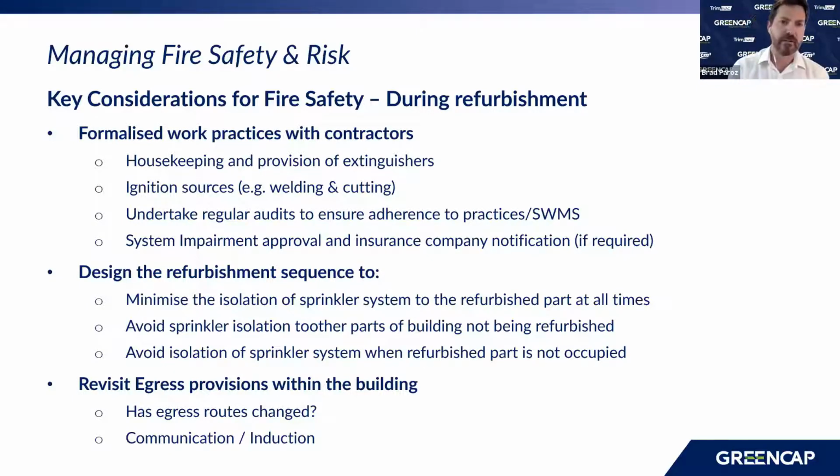Yeah, great. Look, dead right about isolations during refurbishment work. Some contractors will take the view that they'll isolate as much as possible, and thereby increase the risk more broadly to the building unnecessarily, rather than just isolating the work area. They'll isolate an area much larger than that, sometimes the entire building, and obviously cause issues in terms of early warning and fire brigade response as well, if you're isolating critical detection systems or sprinkler systems and so on.